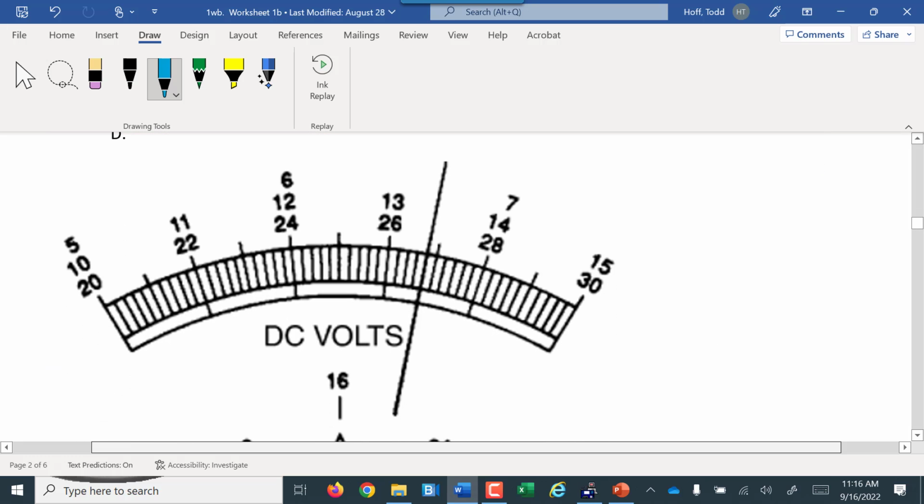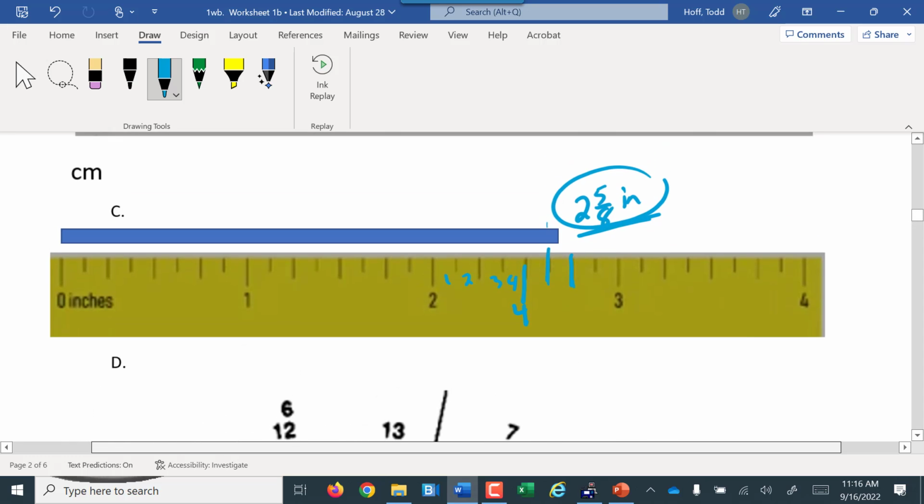Do you guys talk about degree of precision and stuff like that at all? No? Degree of precision is just the capability of your measuring device. On a ruler, it's just the smallest division of the ruler. So that would have a degree of precision of an 1/8 inch.